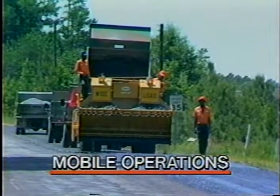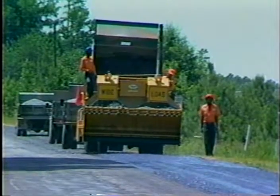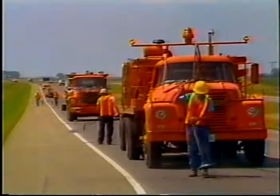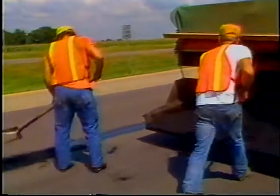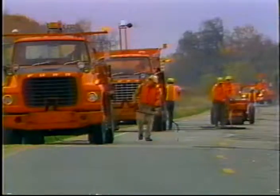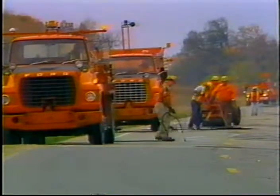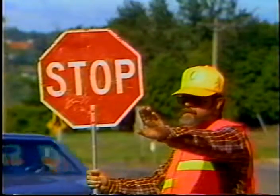Finally, let's look at mobile operations. Generally, this work uses a moving vehicle train with occasional stops of less than 15 minutes. Mobile operations should be used only during daylight hours and at locations that offer good visibility. When the sight distance is restricted approaching a mobile operation on a 2-lane roadway, a flagger should be used to protect the workers and to warn the driver.